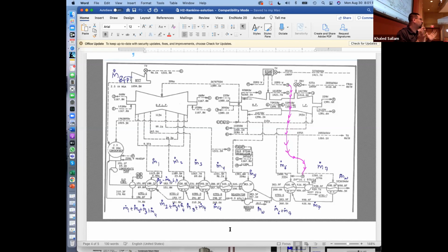That's straightforward. But when there is only one guy heating one guy, steam heating water, all you have to do is M dot delta H of the water equal M dot delta H of the steam. And don't worry about the minus sign. Make sure that this is plus and this is plus. The heating guy equal to the guy that's being heated.